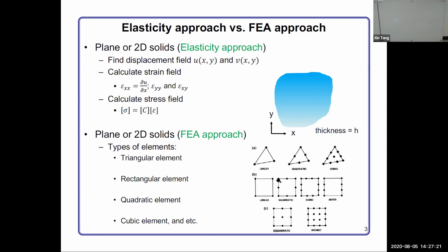So the conditions on the nodes are the first most important data we need to use. Okay, by increasing the node number, we can use higher order polynomial equations to simulate the stress, strain, and displacement, and make the result more precise. And I have talked about the quadratic and the cubic elements in both geometries now.